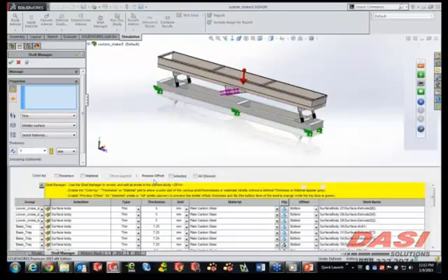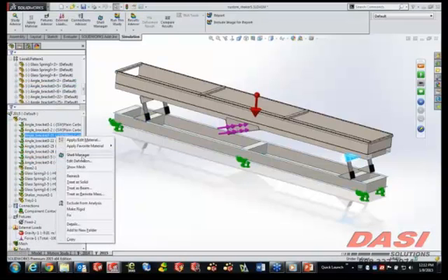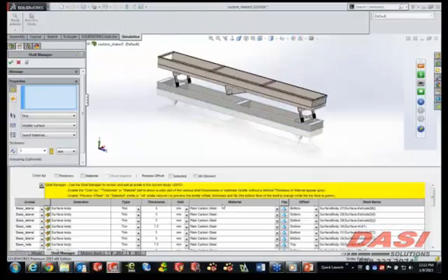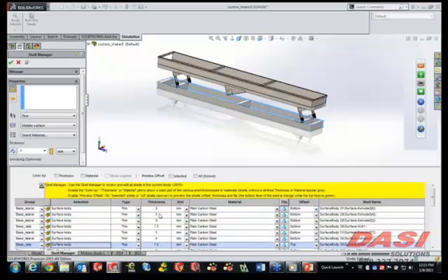Now what the Shell Manager does for you essentially is it gives you the one-stop shopping type of input, much like the Load Case Manager. It's going to show you the different bodies that are participating on the screen. We can see that these bodies can be grouped together, and those groups are effective when we're making changes. Each of the bodies, as we select them, will show up as a highlight on the screen, so it's very simple to see which body it is. And then very quickly, we can see what the thicknesses of each of those are.